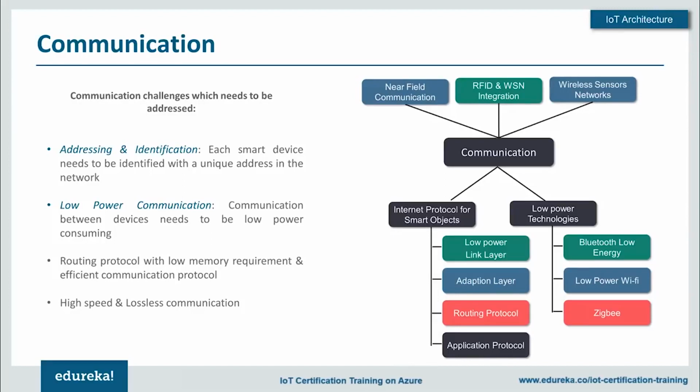Now, the next is low power Wi-Fi. Now, again, the Wi-Fi Alliance has recently developed Wi-Fi HaLow, which is based on the IEEE 802.11ah standard. Now, this in turn consumes much less power compared to standard Wi-Fi devices, and also has a longer range. This exactly is why it is most suitable for Internet of Things applications. Now, any device that supports Wi-Fi also supports IP connectivity, which is very important for an IoT application for that matter. Now, the last is Zigbee.